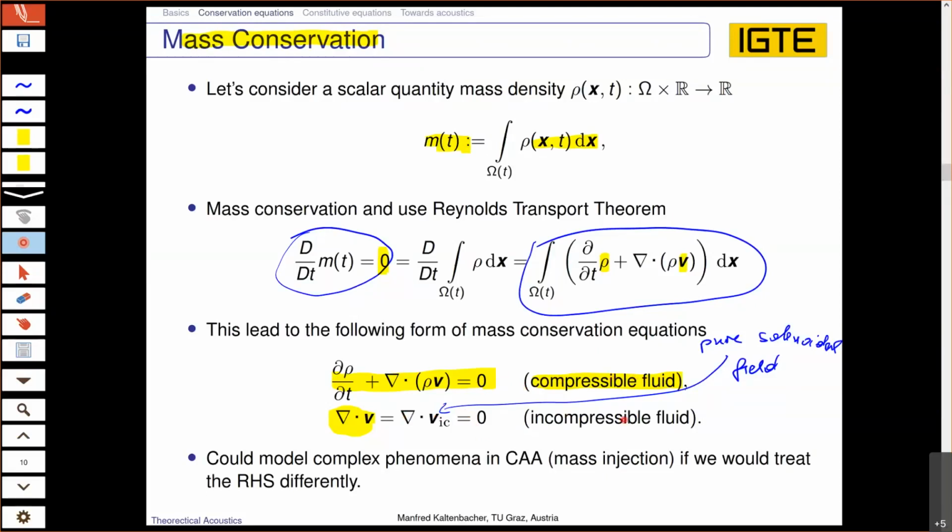Do you know why a compressible fluid is necessary for wave propagation, for acoustic wave propagation? Do we also have waves within an incompressible fluid? Well, we will come up to this, and you will then really see if we describe our fluid as an incompressible one, we cannot have any wave propagation there. So we just model classically our vortical structures.